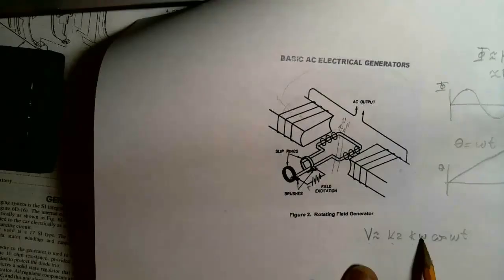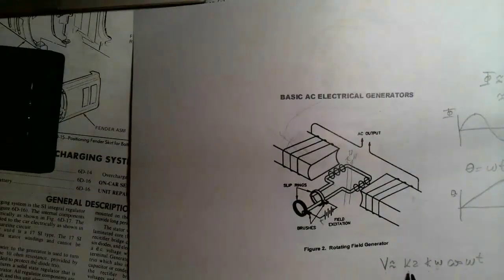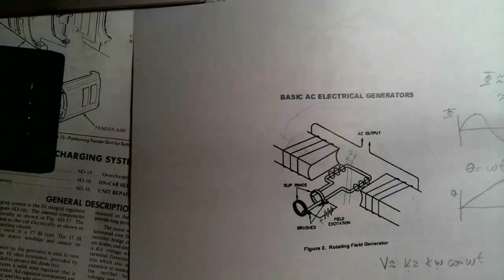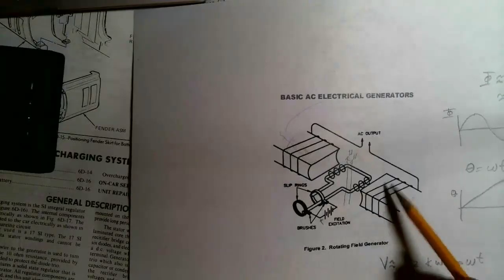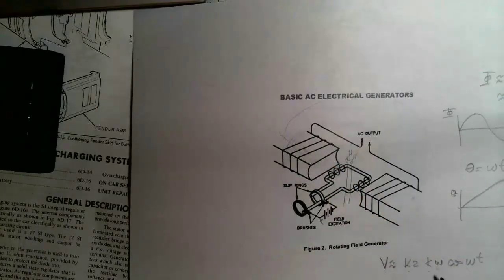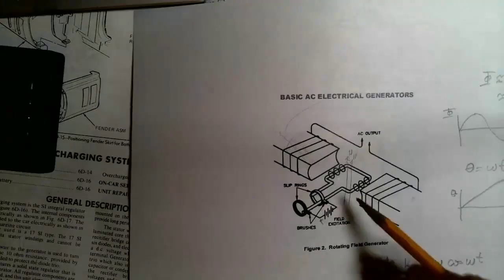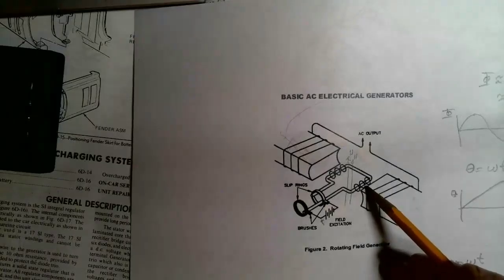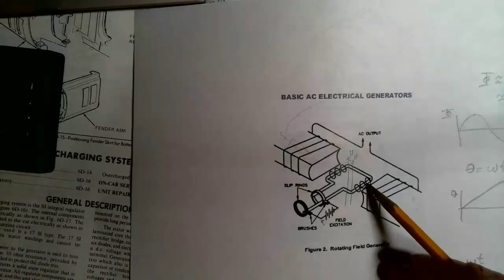affects our voltage. So in these constants here of proportionality, there are factors like how much rotor current do you have, how many turns do you have on the rotor. That certainly determines the magnetic flux. And then how many turns do you have on the stator? What's the rotation rate? The air gap between the rotor and the stator, because air isn't as good of a magnetic quote conductor unquote as iron is. So the bigger the air gap, the less output you get, less voltage you get.